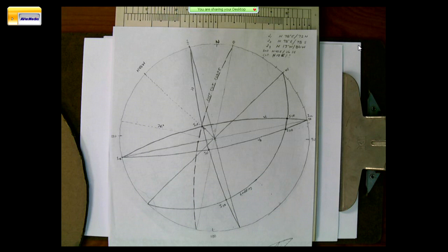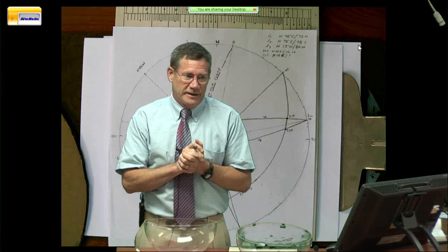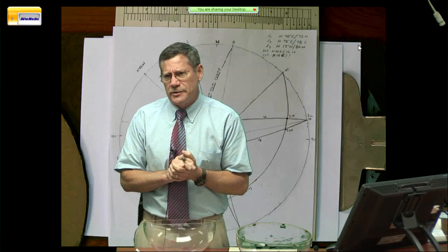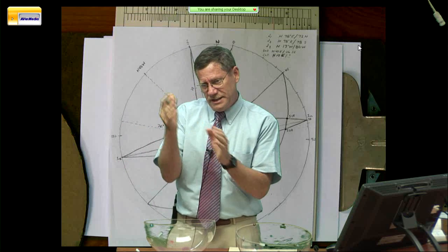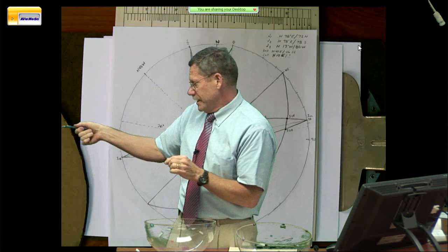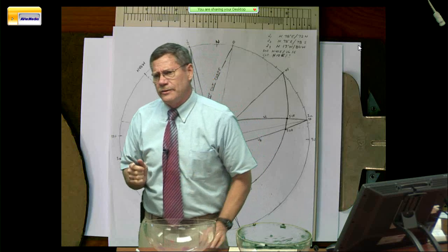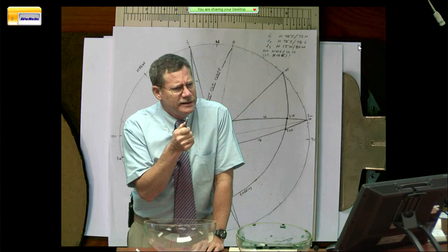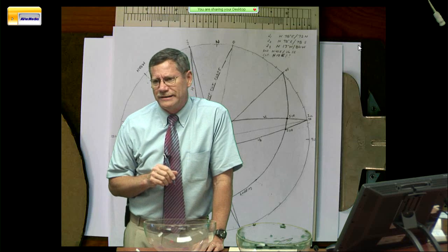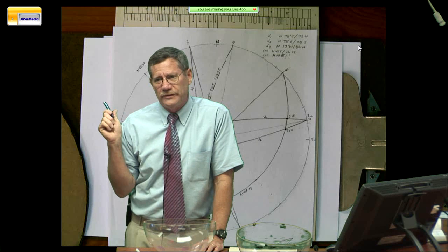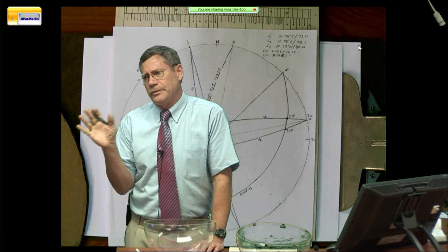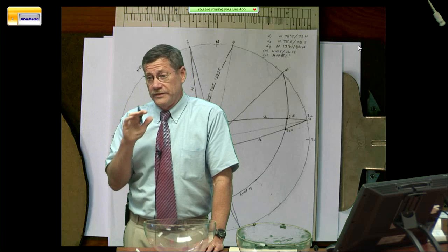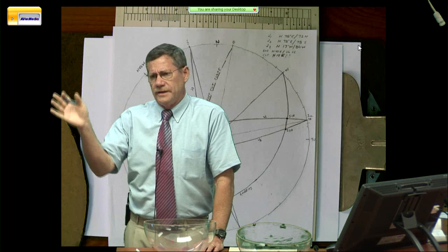That's the easy part. The hard part is, in the real world, things don't group perfectly. You get a lot of data splatter. So you have to end up looking at the data splatter and contouring the poles to these various planes and choosing averages. And then you got to realize where you're going to get the rock slide is where you don't have something that's average. So it's not foolproof. So statistical things like probabilistic assessment are never going to prevent you from having failures. They only prevent you from having a whole bunch of failures.